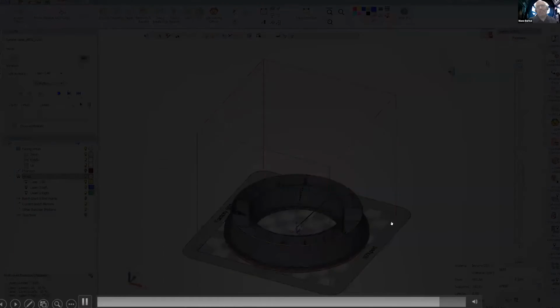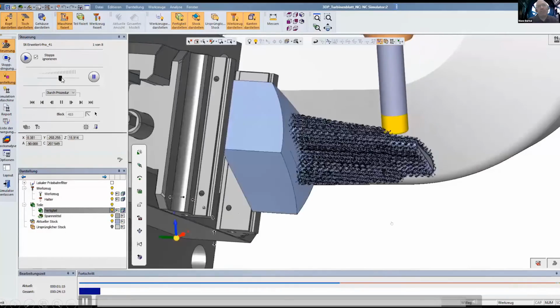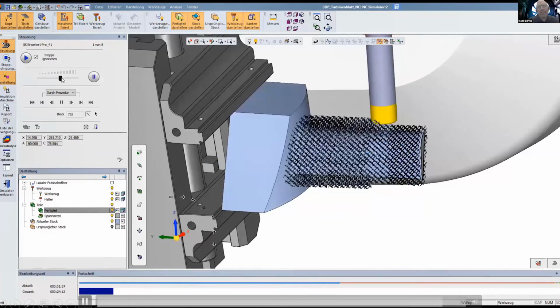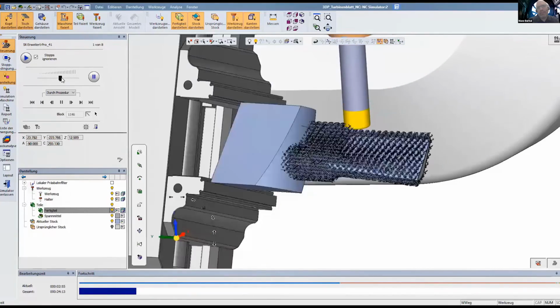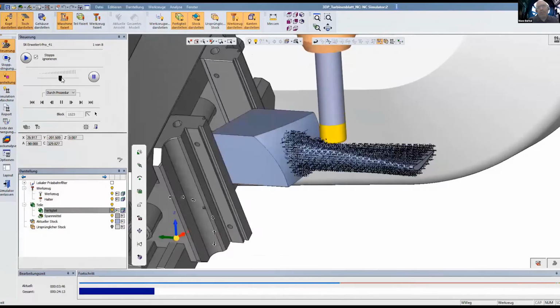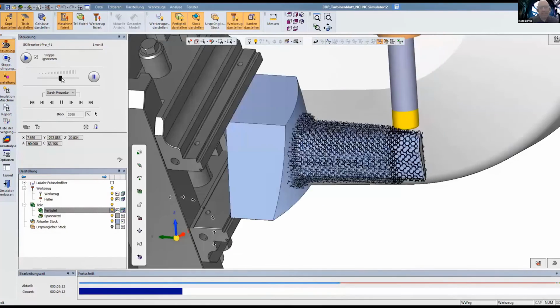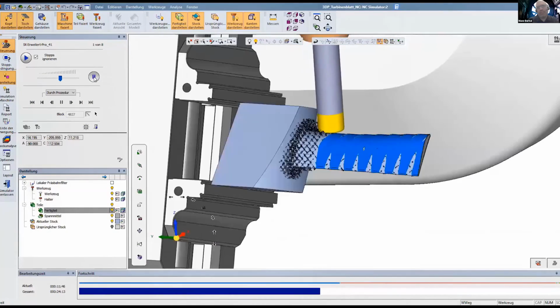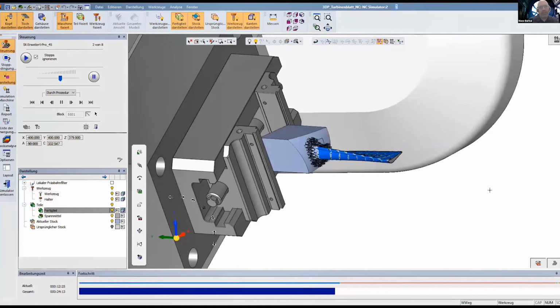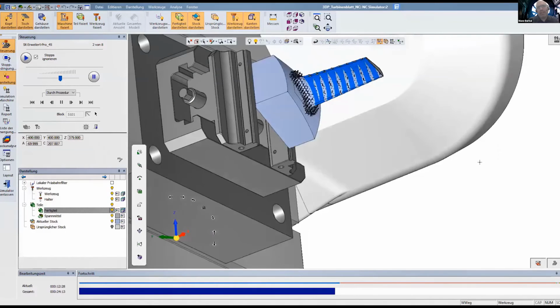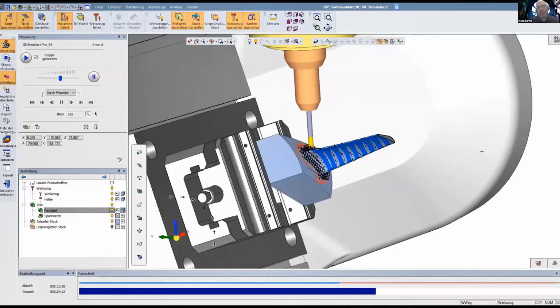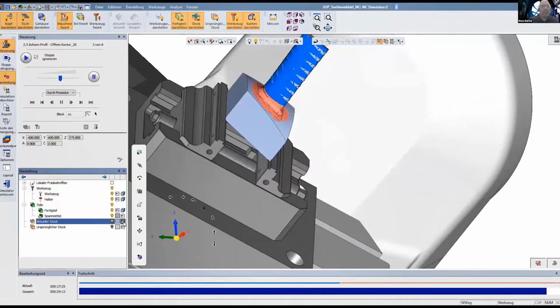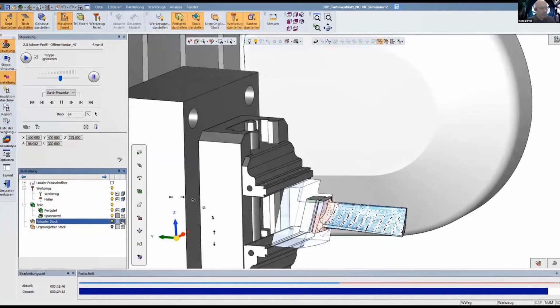Okay, yeah, so I said we can program the post-processing, milling and drilling of the part. So in this case, we're milling off lattice structures that were put on this blade to improve stability of the printing. And you can see actually the simulation of the milling of that part. All right, so that's it.